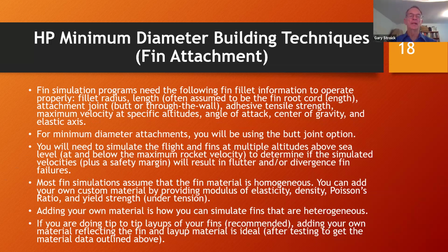And then finally, since we're using butt joints, I would highly recommend that if you're making a minimum diameter rocket, you use tip-to-tip layups for your fins.